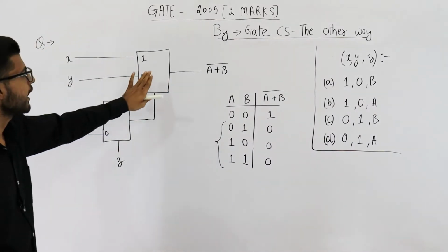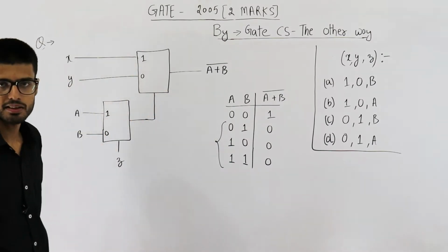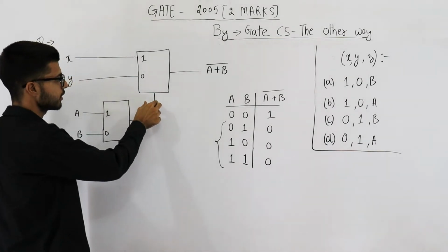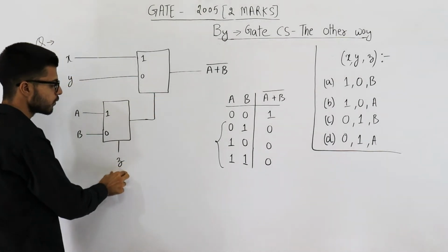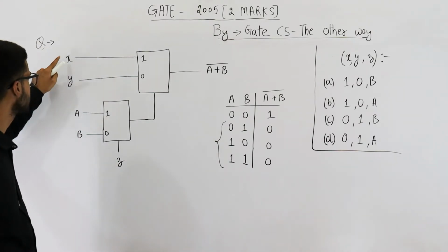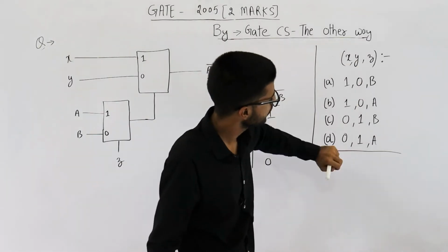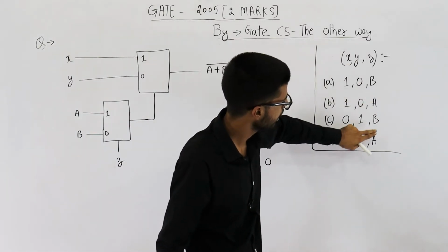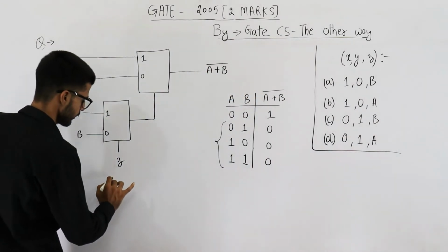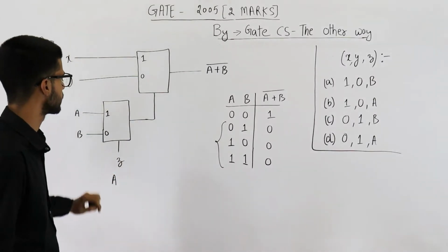Now see, we cannot analyze this multiplexer until we have analyzed this one, because we don't know what this select line is. But here we can know what this select line is. This variable is Z, we need to determine it. X and Y, we need to determine them. Z can take 2 possible values, A and B. Okay, let us try with A. So I'm connecting A here.